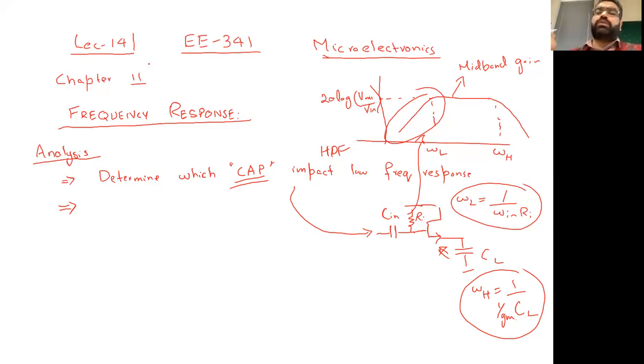We also saw in the last lecture something about the parasitic capacitance. Whenever we do the low frequency response, we will ignore the parasitic, or transistor, capacitances CGS, CGD, CDB, and CSB. We will not consider those capacitances which are inherent to the amplifier. So we will ignore them. Let me rub this so it's not confused.